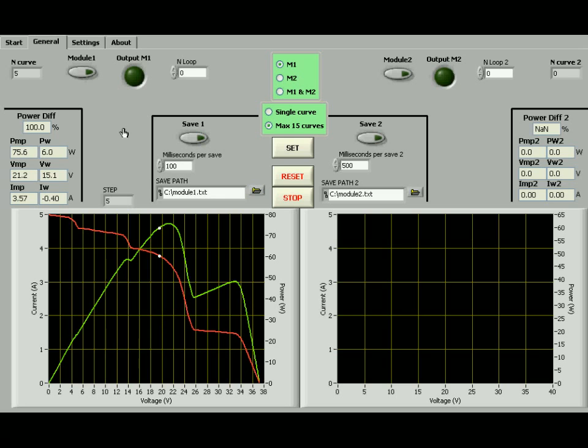Table mode allows us to load any type of curves, and we're not limited to normal and shaded curves defined by the exponential equation. We can therefore load curves that we have measured from real models under different conditions, like shades, cloudy periods, or manufacturing defects. For example, like the one shown in the graph right now, which is a curve we measured in a model with shading.